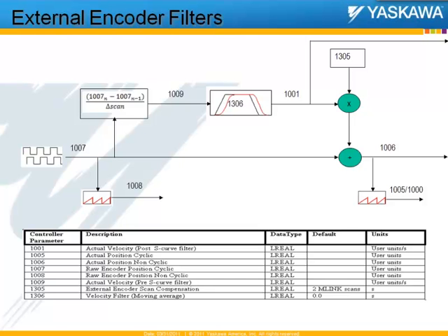Just a reminder, this block diagram, which I think is very useful in designing your application program, is available in the PLC Open Manual for MotionWorks IEC 2.0. The 2.0 was just released last week, and this block diagram is available in the help. Now, these parameters are also available with older versions of firmware starting 1.2.3, but you may not see it in older versions of the software help. This has been made available only in MotionWorks IEC 2.0, in the help.